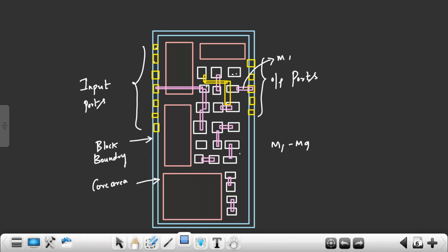So that is, the sequence will go only based on how many layers it is going through from one layer to other layer. So like if I completed M1, then I can only use M2. If I completed M2, no, it's not like that. Your tool will do based on the timing, right? Higher metal layers will be having less delay. Lower metal layers will be having more delay. So whichever routing is coming in the critical path, it will use higher metal layers.